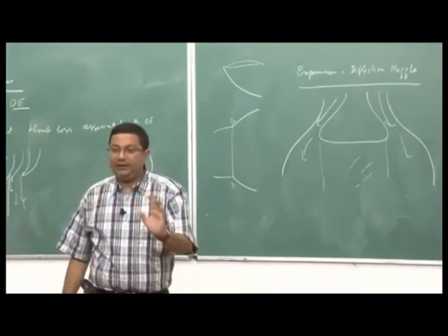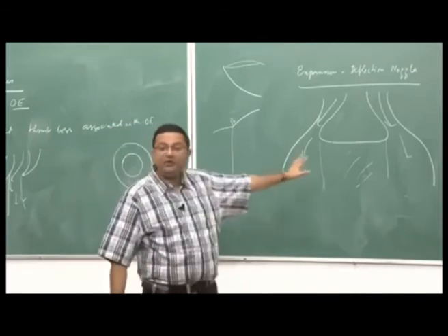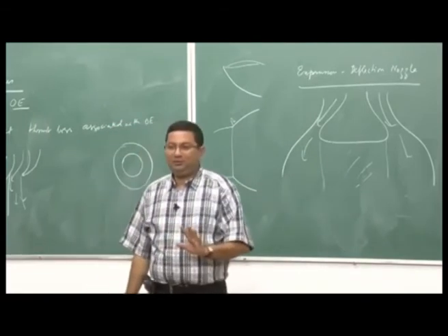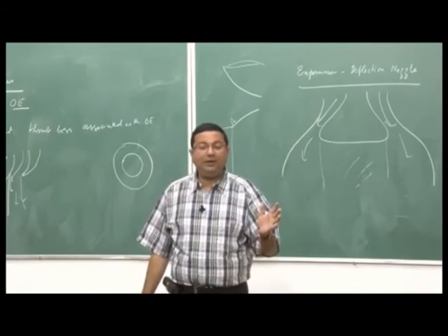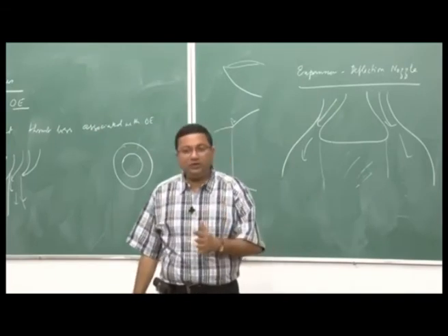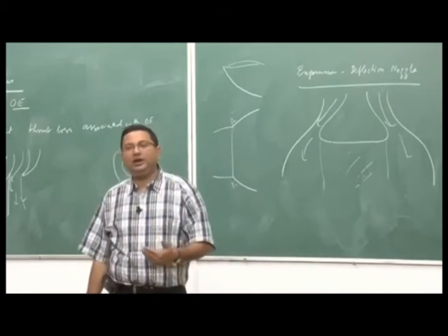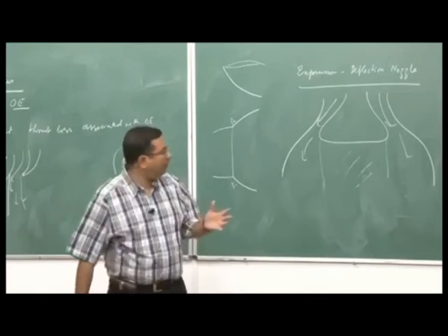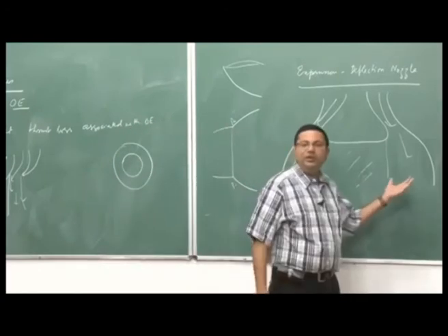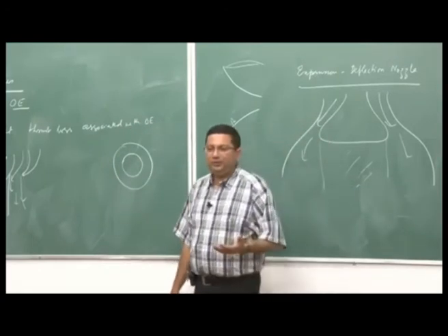And as we have said, particularly this over expansion case is more dangerous, because you can have a shock wave going in, and that will have huge losses, because there will be shock induced losses, there will be shock boundary layer interaction leading to flow separation. So, there can be very, I will say, devastating phenomena occurring in the flow,